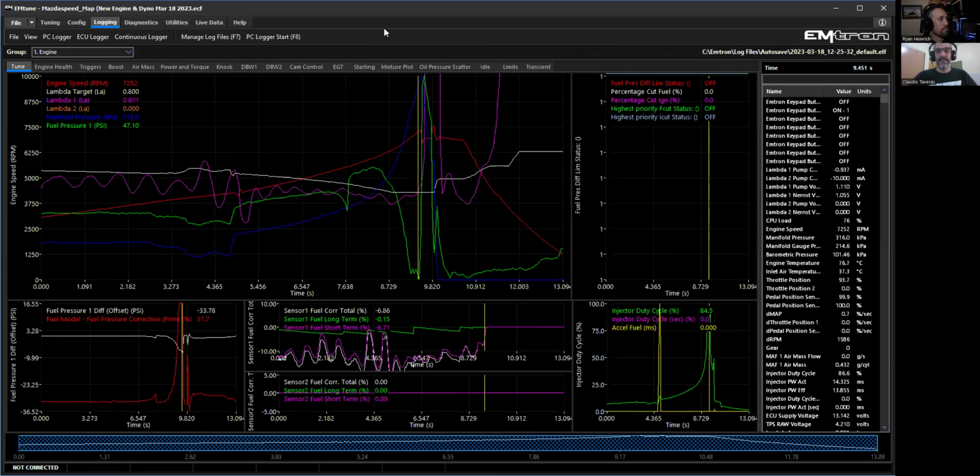I actually have a car like this, and one of them is doing this thing where we have a pump and it does not have a check valve into the section. So you've got a pump, and then the second pump goes to feed and it back feeds into the primary pump. And it does the exact same thing that Claudio is showing right here. So it comes down to the use of a check valve in a multi-pump system is actually very important.